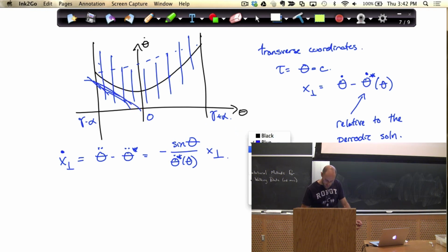orbits, but things sort of diverge on this side and they converge over on this side, okay? So instantaneously, and this brings up a point that you were raising not too long ago, these trajectories can be diverging, but I can still find a Lyapunov function that over the period is going to prove stability, right? So it's diverging locally, it's converging here.